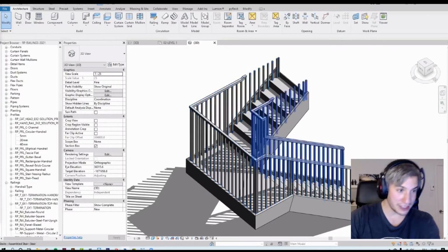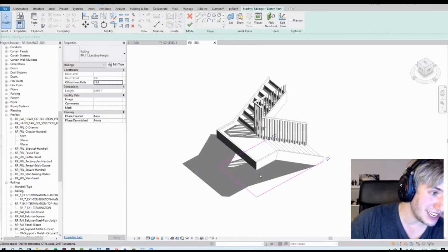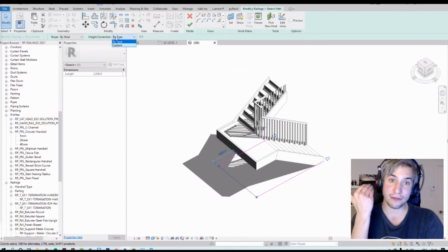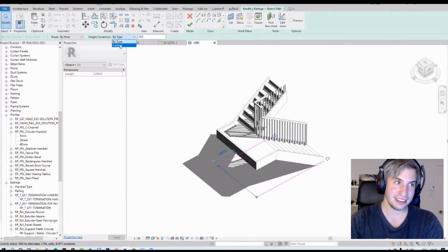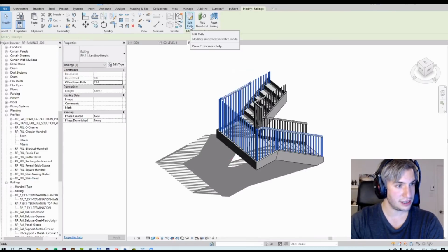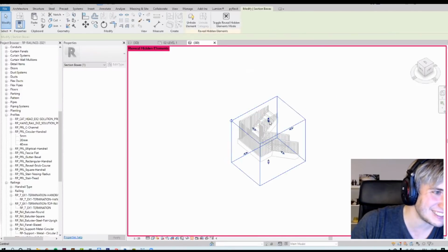But that's not all. That's the way to do it, but what I've learned recently is that there's also another way you can do it, which is to edit the path here and select a purple boundary line, and you have the height correction. So you can do it for each line segment. That's when it gets tricky. But you can select custom here, and let's say I'm going to put 700.